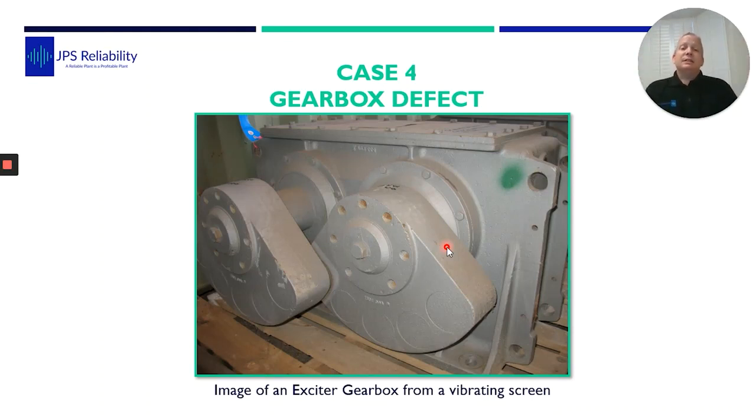In this particular case at this site, they were having problems with gearboxes failing. Their current way of detecting the mode of failure was on operator walkarounds. They would use a temperature gun, and when it was hot, they knew it was going to fail within the shift. So the issue here was that the detection to the PF interval was too short, because then they would panic around and try to get it fixed. We offered to do a vibration analysis survey to see if we could find a defect.